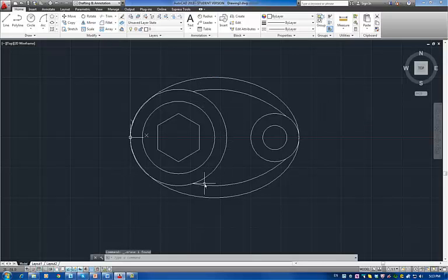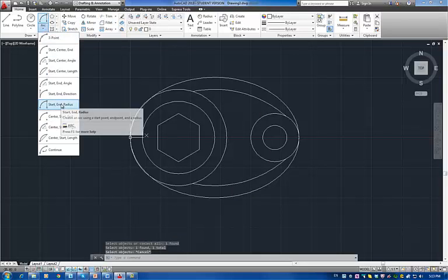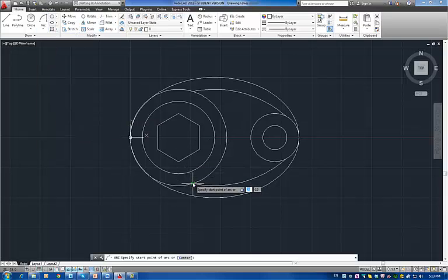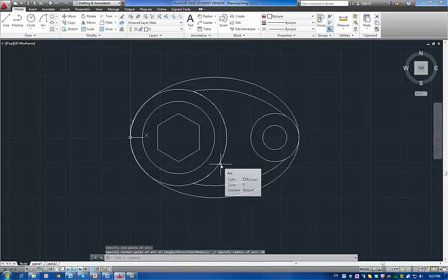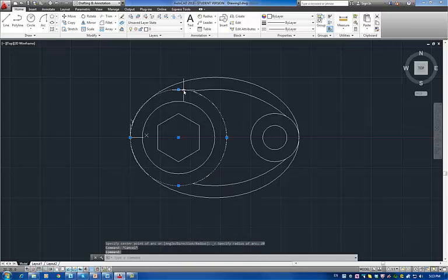And now I can do the same thing to create these parts, but I can also use these two as slicing tools. Let me see if the trim will work. So if I say trim, one cutting tool, the other cutting tool, it doesn't want to select two things. So I will do the same thing. Arc, start, end, radius. Again, here. And then the other one there. And this one is 20. Radius is 20. And then I will delete this one.